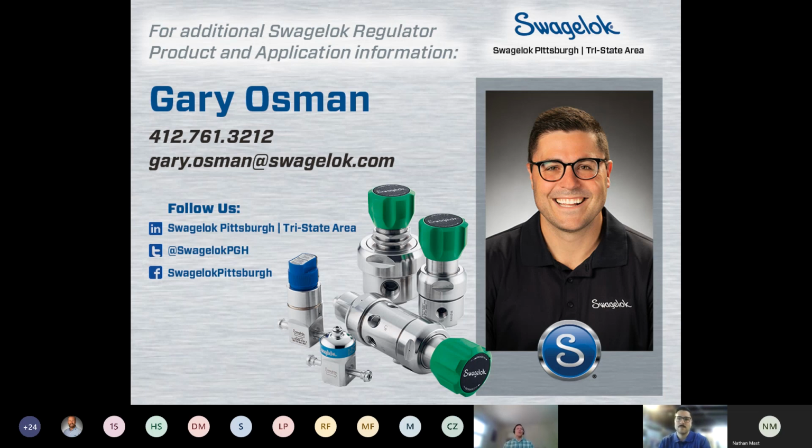Now the one benefit of that is that the JT coefficient for those gases at the temperatures and pressures we usually encounter them is actually pretty low, so they heat up slightly. Now, if you have massive pressure drops, obviously you'll see big changes. But similar suggestion, you would just go the cooling route versus heating if you needed to.